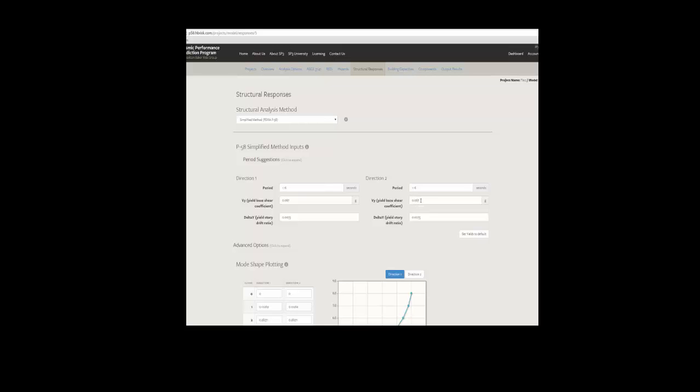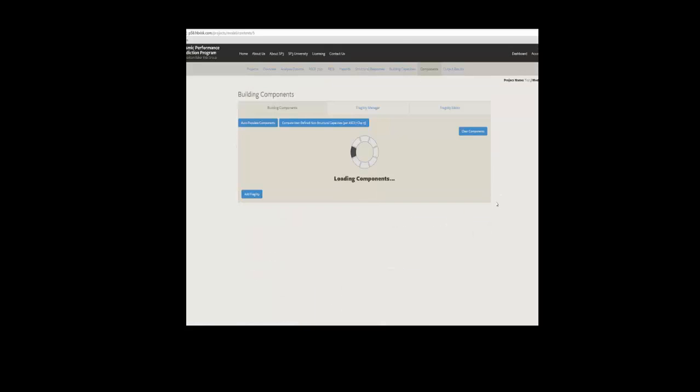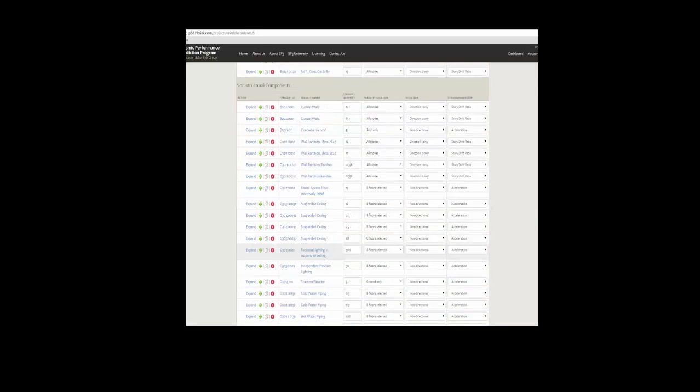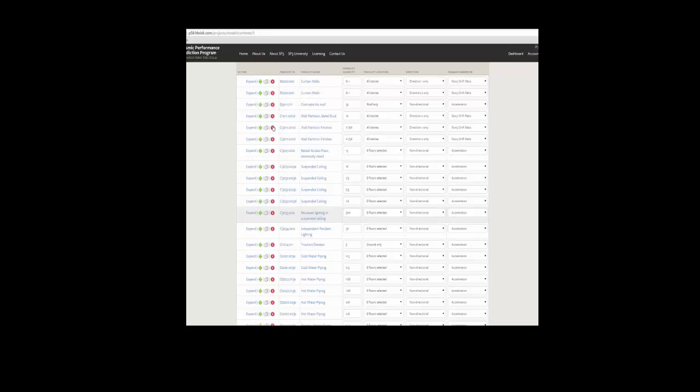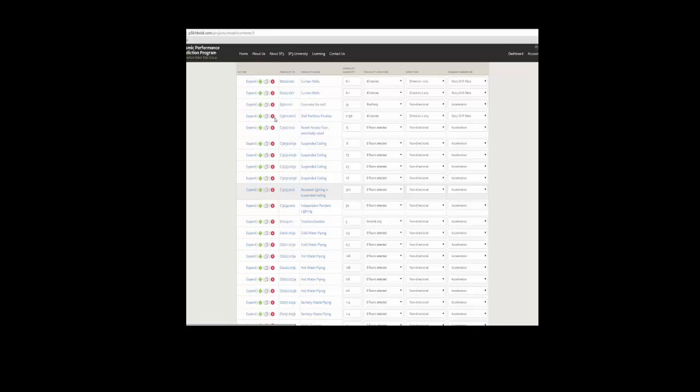Yeah. So we're setting it up so that if you have a default strength of 7% and you change it to 50%, then when the reviewer looks at what we're calling the review mode model, which you'll provide a link to when you submit your USRC rating, if you use SP3 at least, this box will be yellow, and next to it it'll say the default was 7%, so the reviewer can see that they ran it with 50%. And also with components, if I say my damageable components are the wall partitions and finishes, and I delete those, it'll flag that those are supposed to be there, but they're not.